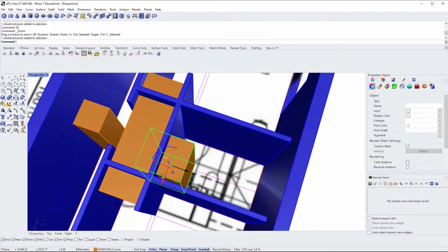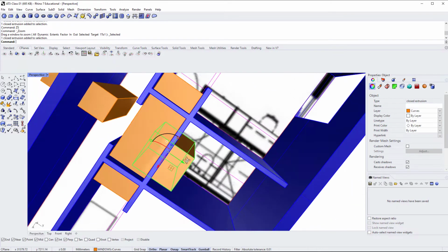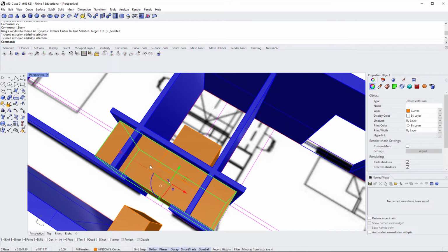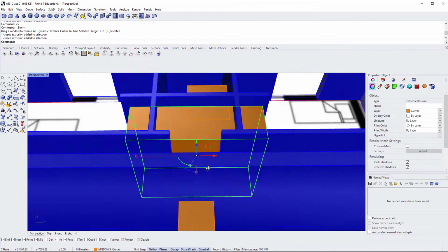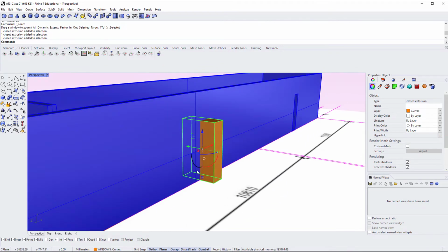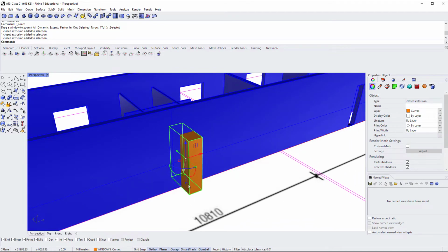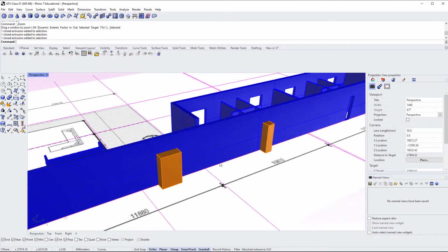Then you've got this one here which goes into the ensuite, and I've just extended it to be wide across so I don't have to have two of them. The window follows the same principles we were doing before, and in this instance, I've rationalized these windows to be 2.4 high by 600mm wide.